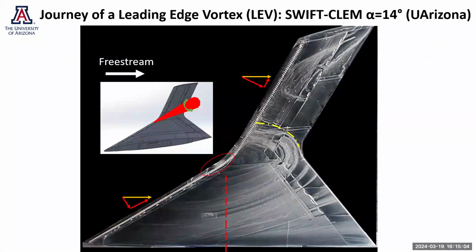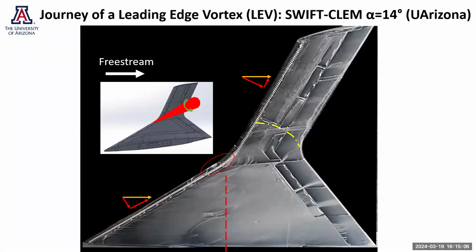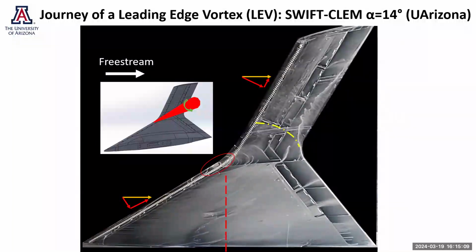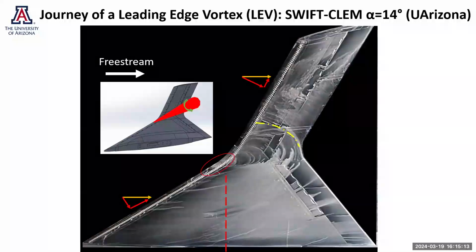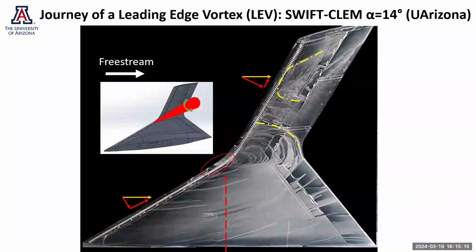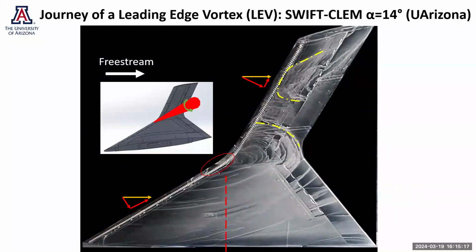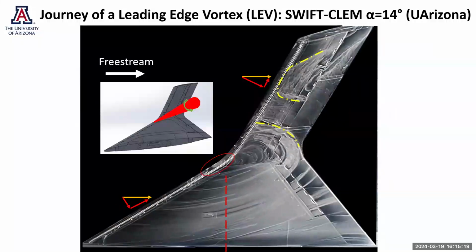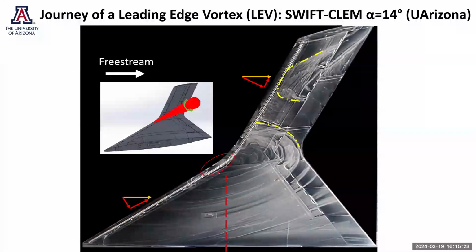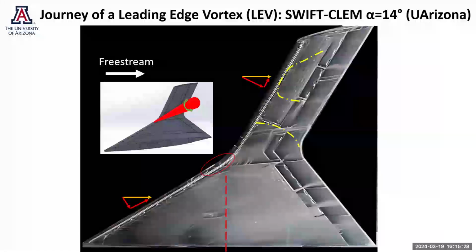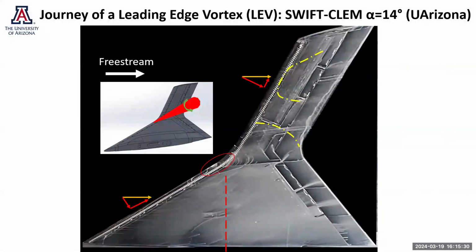So that's the implication of a crank, that we are kind of forcing the vortex liftoff location. Further on the outer wing, you can see some interesting structures forming. The streamwise direction is towards the right, yet you see some flow reversal in this region, and you can see some curvature over here.